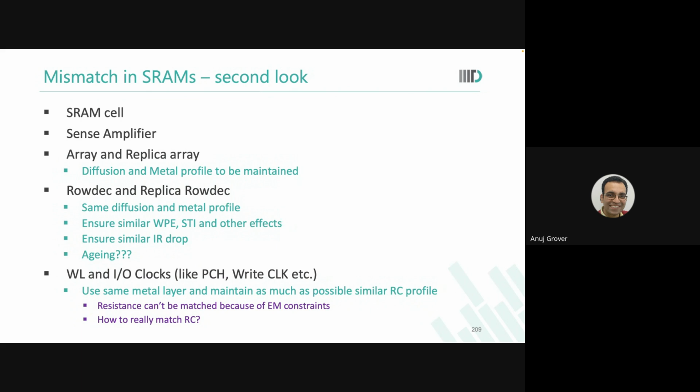That is what you have to ensure. If you do make any variation, for example, you need to program something inside the memory cell, you can't change metal ones, you can't do anything like that there. So what you will do, you will extend the poly out. Just extend the poly a little bit. And then you will do something outside the memory cell. Nothing inside the memory cell. Okay? So if any one of you takes up a project on designing these replica cells, that could be a very interesting learning exercise to understand how this matching is done and ensured.